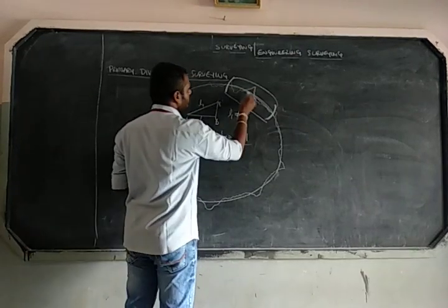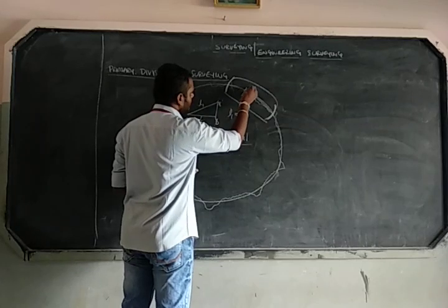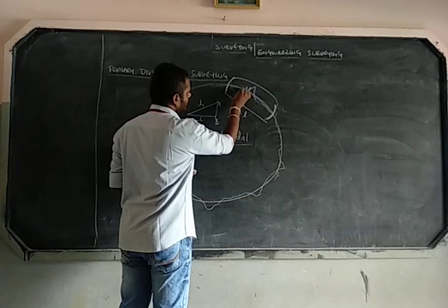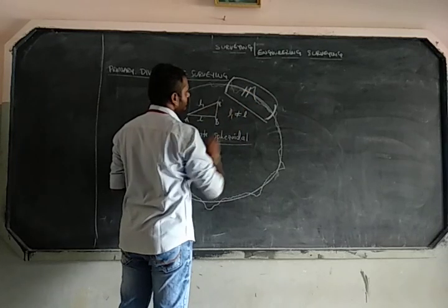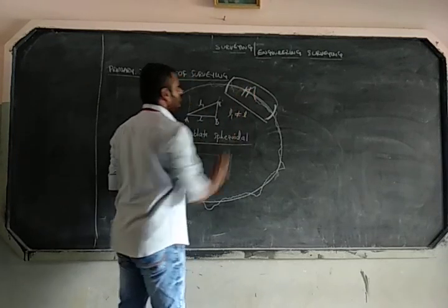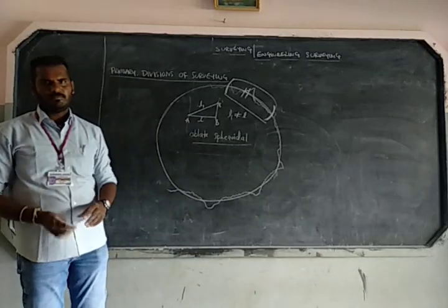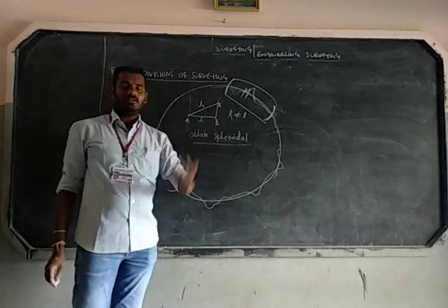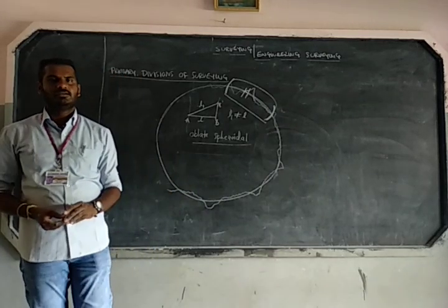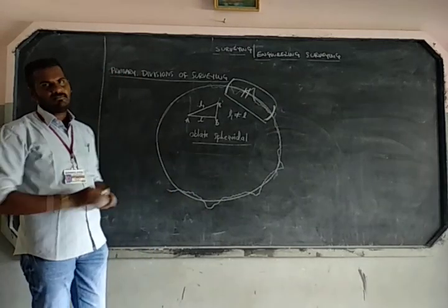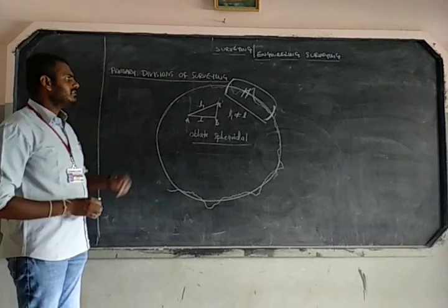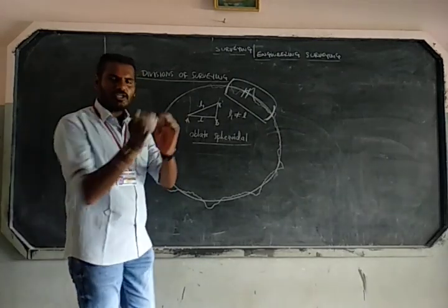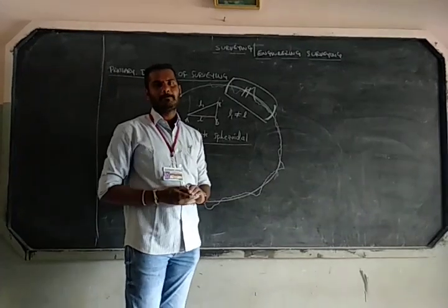Because of this, if I want to measure the distance between these 2 points, the assumed ground is exactly straight, but the actual ground is not straight, it will have some slope. Therefore, for the distance measured over the ground level, you will get some errors. That is the first thing. And the second thing is, now I am going to talk about a practical condition.